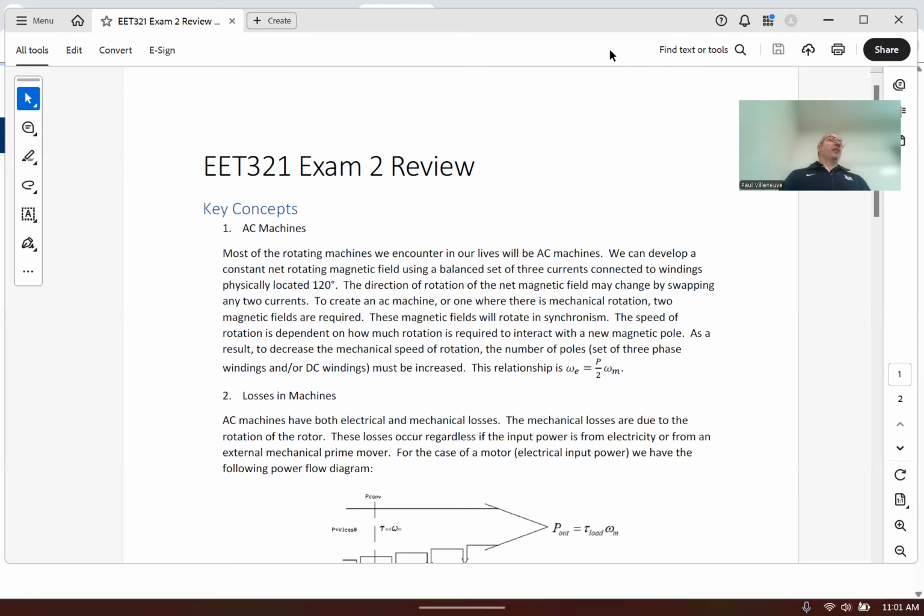Impedances, because it's a delta connected, Y connected, and we're assuming equal, it's going to be multiply or divide by three. The only time you're going to use a square root of three for power is when you snuck in some line-to-line quantities, okay? But ultimately, it is based on three times the individual phase quantities.